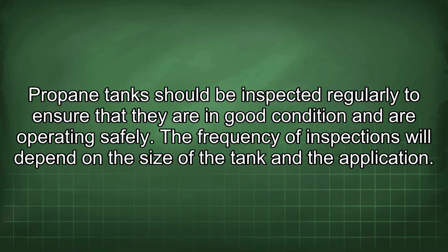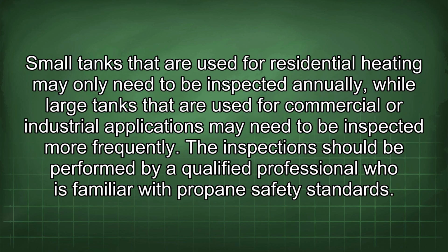Propane tanks should be inspected regularly to ensure that they are in good condition and are operating safely. The frequency of inspections will depend on the size of the tank and the application. Small tanks that are used for residential heating may only need to be inspected annually, while large tanks that are used for commercial or industrial applications may need to be inspected more frequently. The inspection should be performed by a qualified professional who is familiar with propane safety standards.